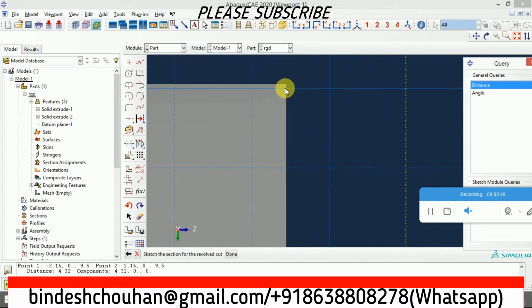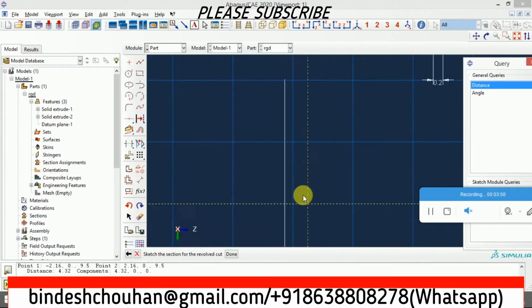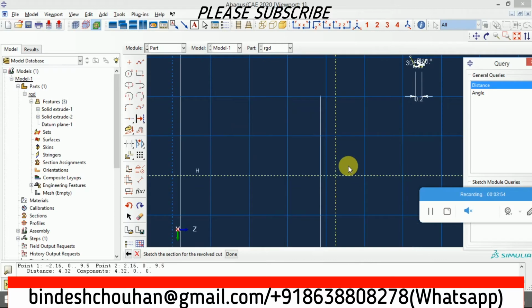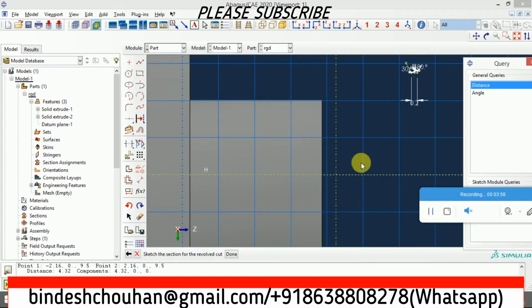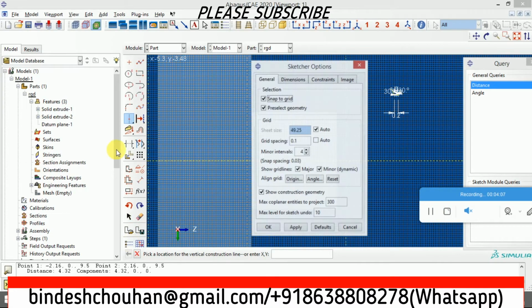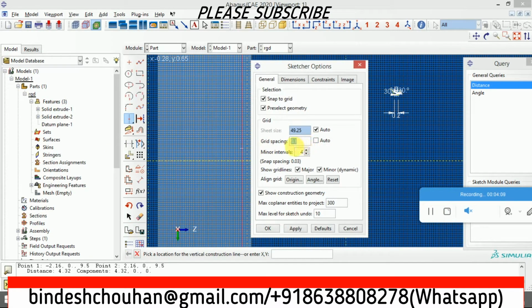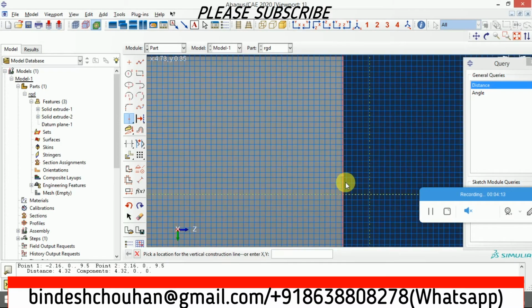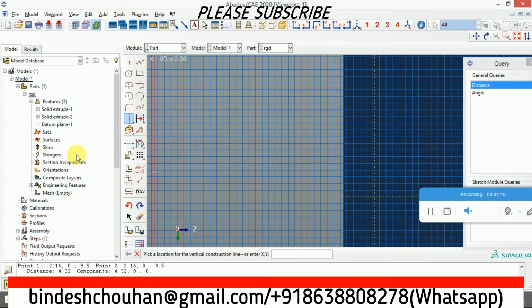For that I need to draw a construction line again. I'll delete that construction line. Here I have reduced the grid spacing. I have made it 0.1 here. You can do it like this. I'll be setting one more construction line. Later I'll delete this construction line.